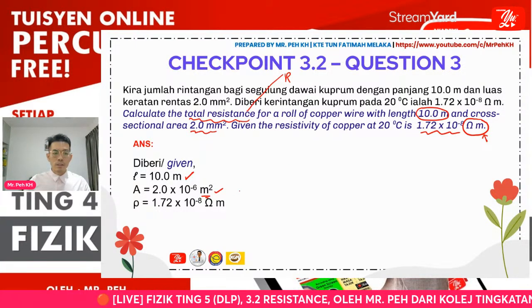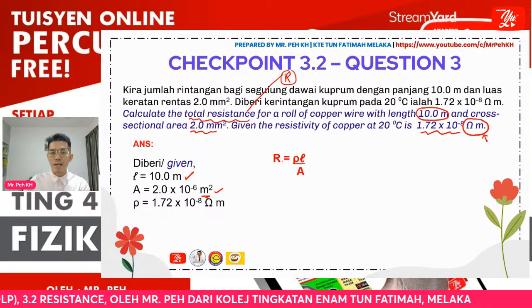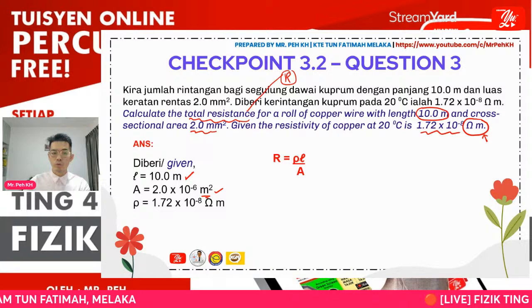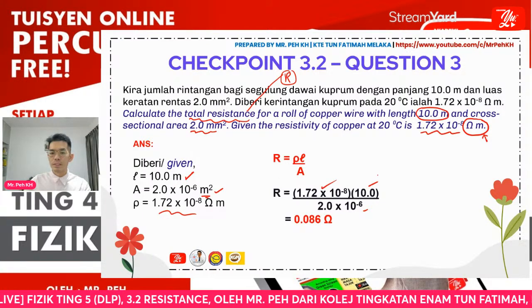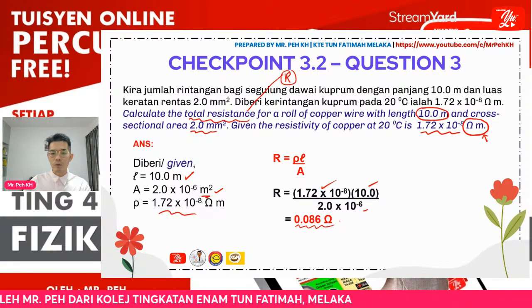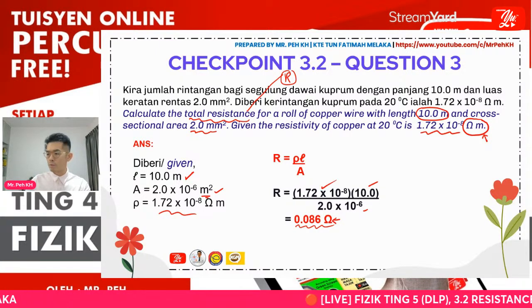Here the question asks about R, so this is very easy. We just apply the one and only formula from learning standard 5 that we went through just now. The rho will be this value, L will be 10, and A will be this. The most important thing is to change to SI units. So you get this value, 0.086 with unit ohm. Ohm meter is for resistivity, and the resistance will be in ohms.